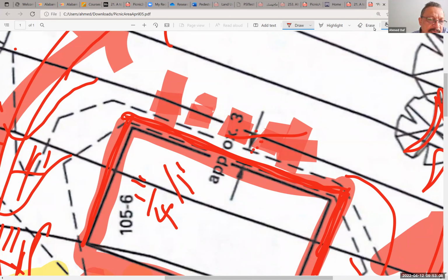Why? To just make water go through. It doesn't collect on the pad. If it is completely flat, water will collect on it. So actually we make a very slight slope, you won't even feel it. 1/4 of an inch in every foot.